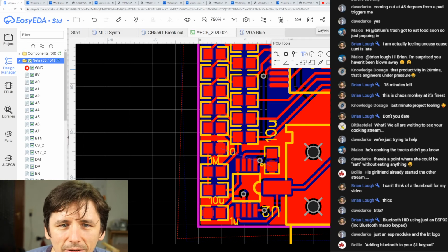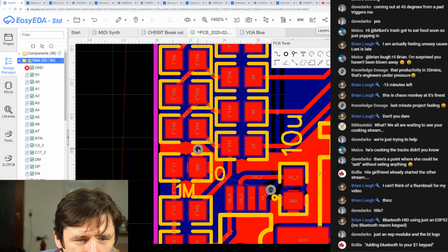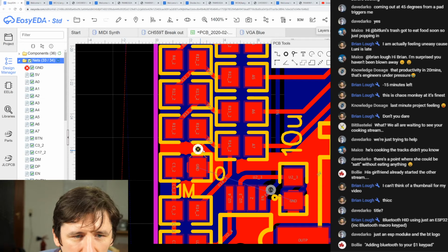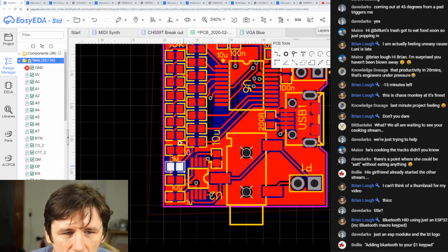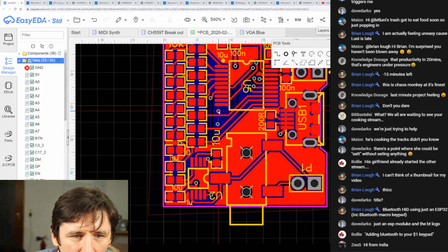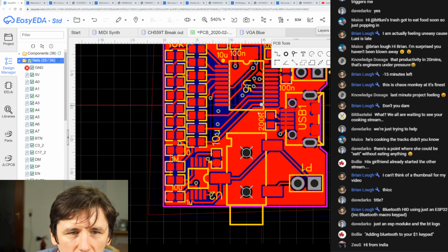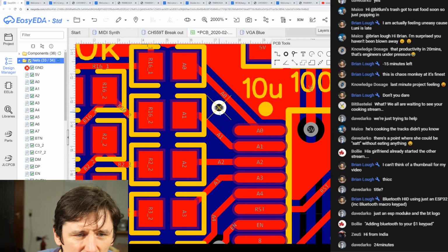Yeah. Okay, now we have to set some vias here, or vias, or whatever you like to call it. We will do a ground. This will destroy our silk screen, so I will put it somewhere here. And now we have to set GND. And now it's connected, and I will put some vias here, there, and there, and there to not create some, oops, it's too close.